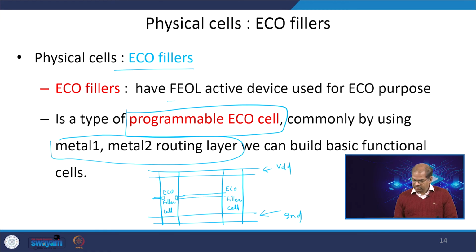If multiple fillers are needed, then you connect it back to another flip flop. So, this is the flip flop 1 output and flip flop 2 output. This is the launch and capture flip flop. In this case we are adding delay to the actual critical path, and what is the advantage of this one? We are just adding some metal lines.